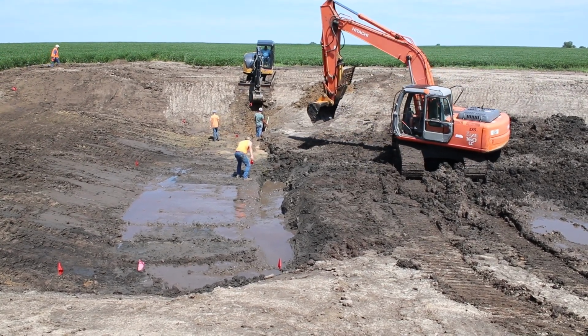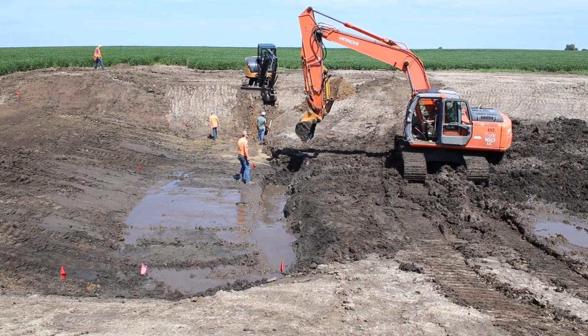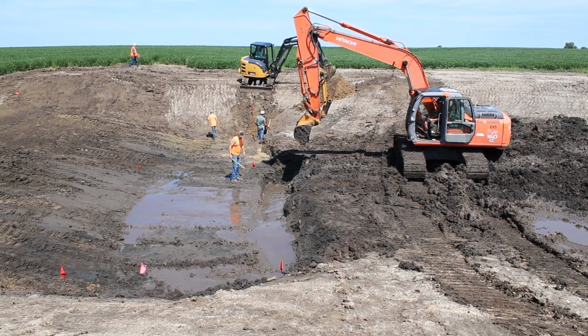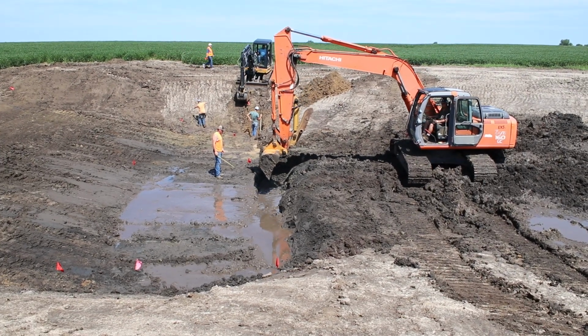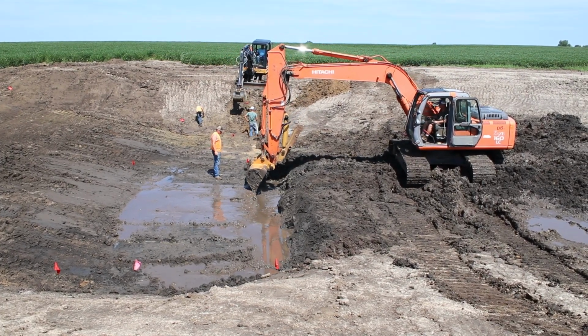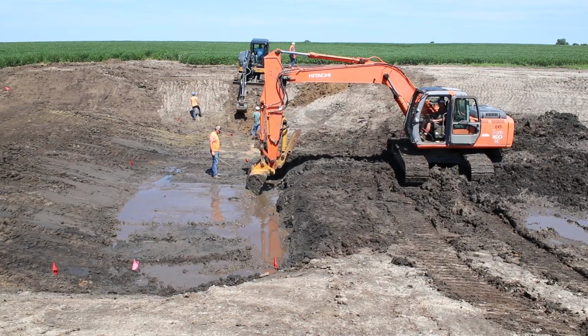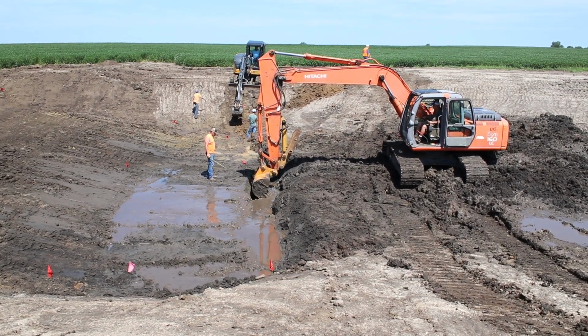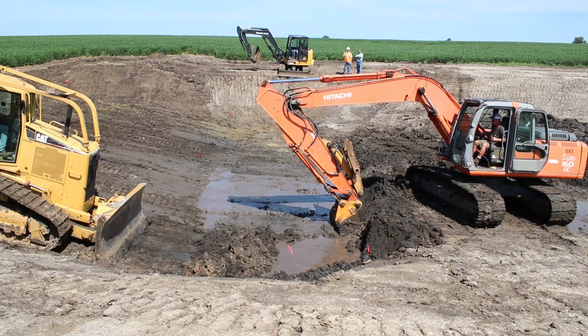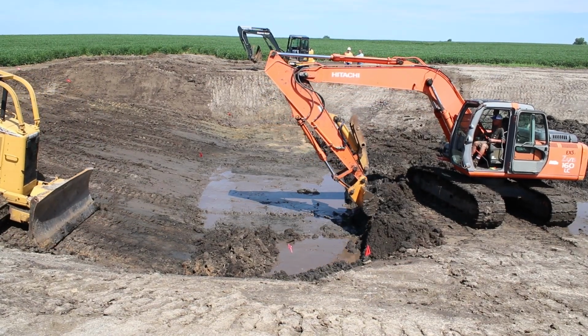A common hurdle when excavating within a channel is managing tailwater during construction. Water can accumulate within the excavated area, either by surface water or base flow. In this case, a sump or low area for water to collect can be dug out, and a pump can be used to pump out the water. Even with the pump in place, water continued to be a challenge.